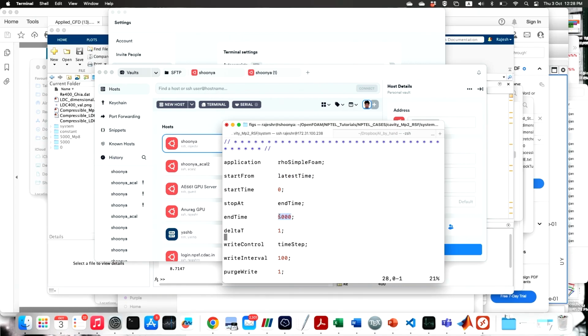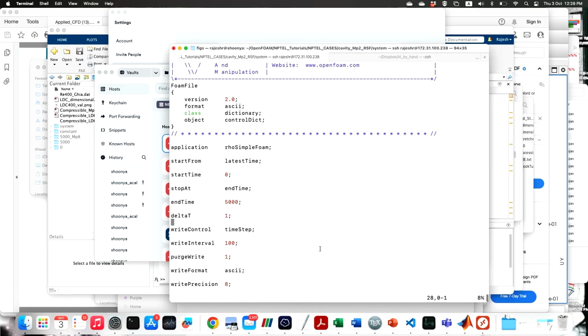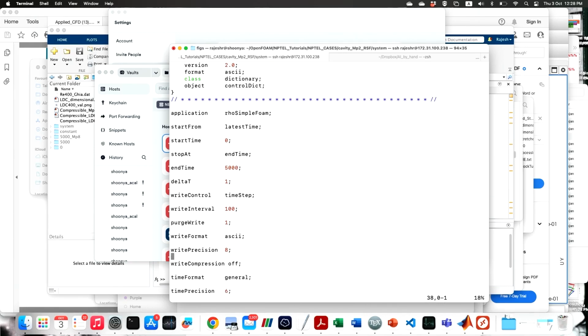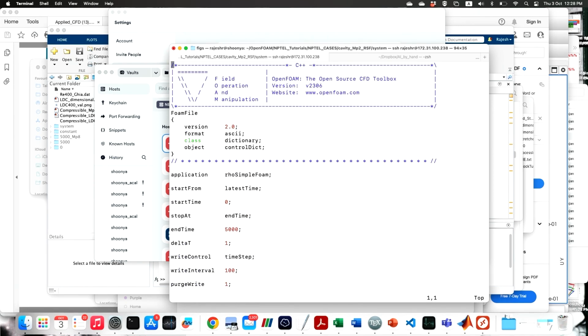You will learn from experience how this works, and how long you have to simulate. Typically around 20 flow times or so is good for the flow to evolve, but it may require more also. And this is when we are writing, and all other things are simple.